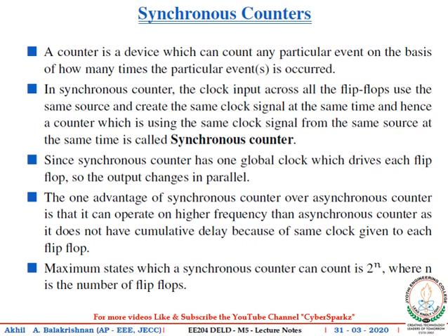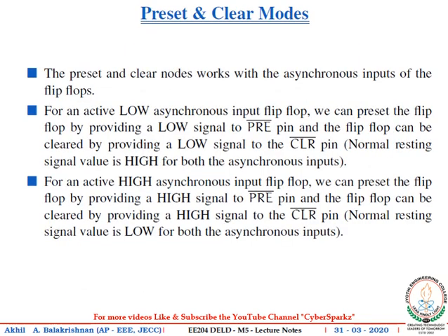Here, the propagation delay of a synchronous counter is equal to the propagation delay of just one flip-flop and the propagation delay of the gates involved, if any. Hence, synchronous counters can operate at much higher frequencies than asynchronous counters. A synchronous counter can also be preset to any desired starting count.